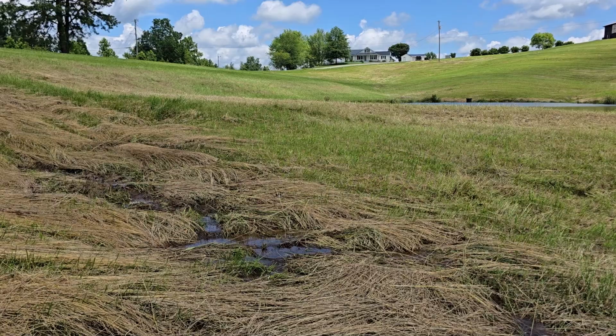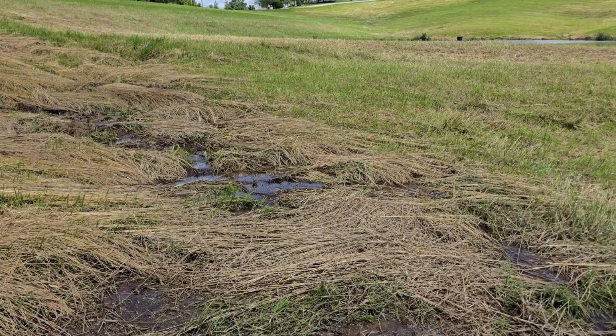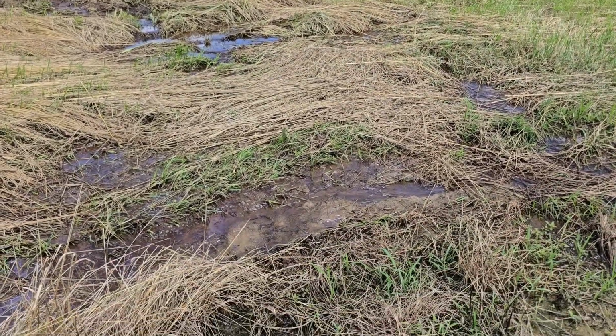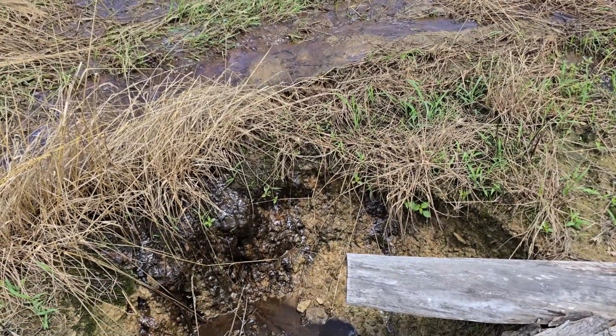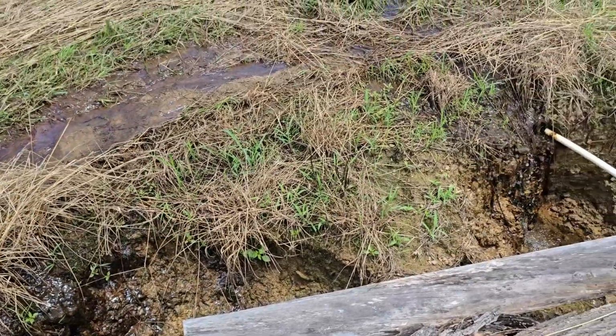The water you see is standing in the ruts left by the tractor that was driving through saturated soil downhill of the overflow pipe. I follow the flow of water from the pipe downhill where I find 2 head cuts. The head cuts are moving uphill and will eventually drain the pond unless they're controlled.